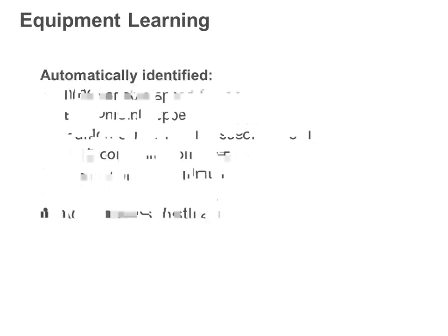It's fairly intuitive and easy to use. Along the top bar of the stat, you have your normal basic data, time, date, outdoor temperature. Right in the middle of the screen, in the biggest font, you have the indoor temperature that it's currently measuring in the space. If you want to change set points, it's on the bottom right. You can press the heat button or the cool button, and little arrows will pop up so you can go up or down on those set points.